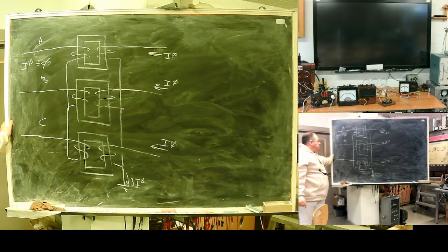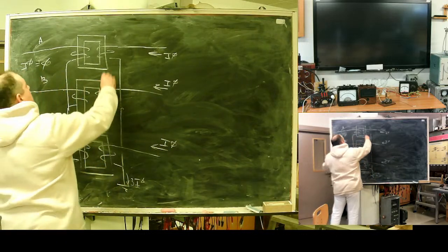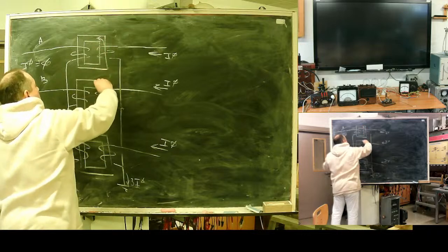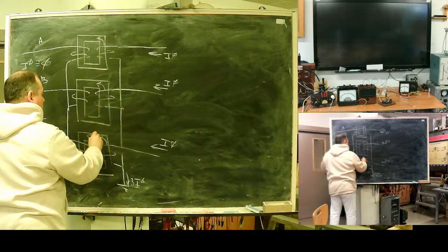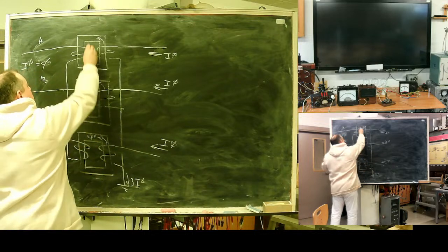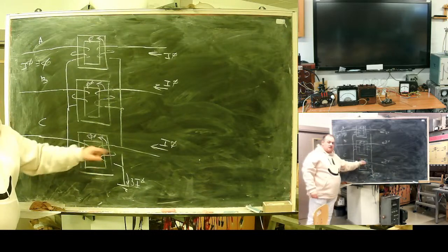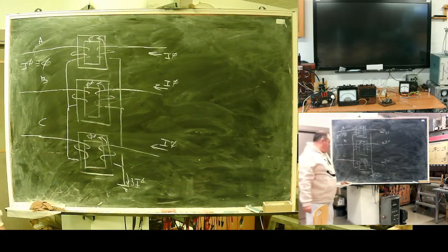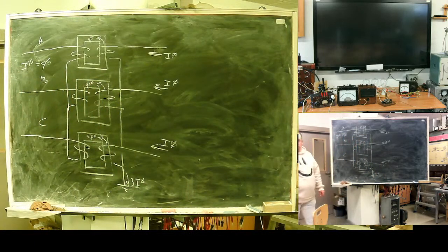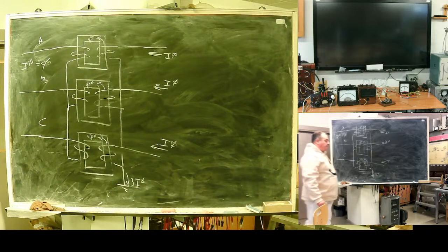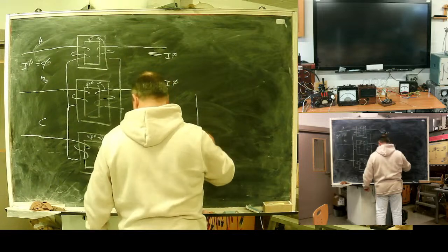What happens? Zero sequence flux can freely circulate in the cores, in the steel cores of this transformer. We have a closed steel loop. If we have a closed steel loop, we have good magnetic conductivity, meaning high reactance. We will see what we will see.